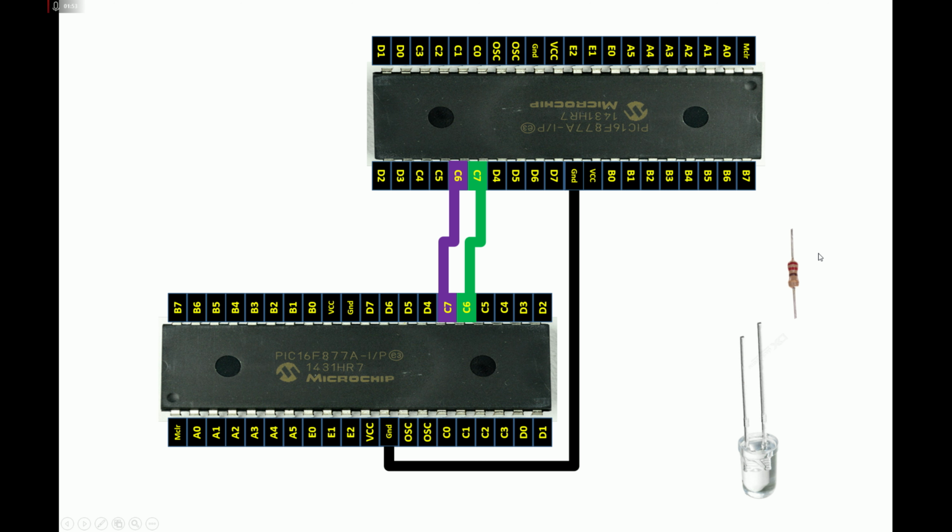That's an ideal value. So the shorter pin of this LED is the ground pin, while the longer pin is the power pin. So you can connect the ground pin directly with the common ground of both the circuits like this.